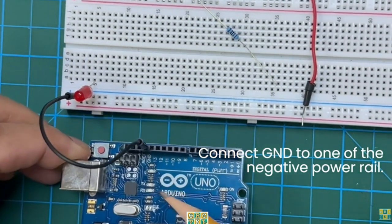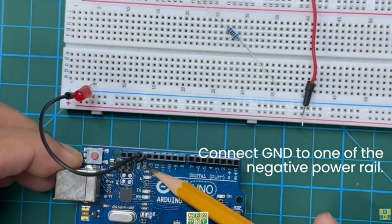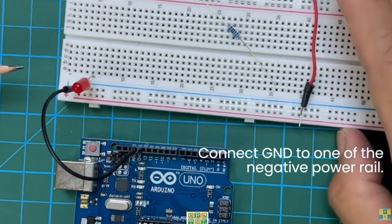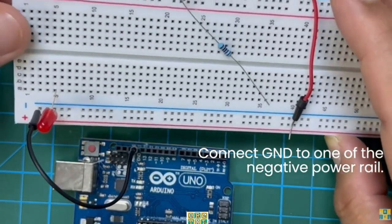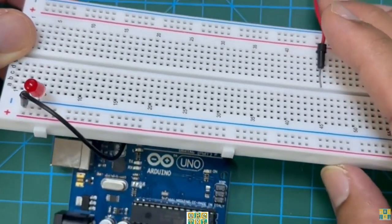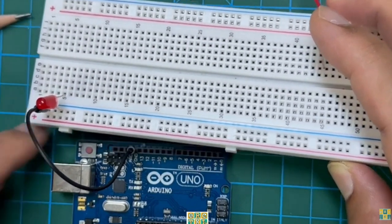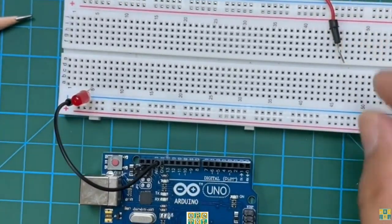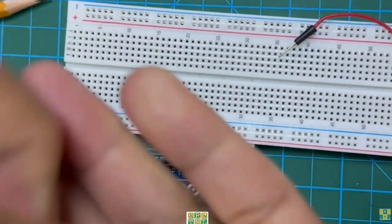So the negative horizontally are connected together. So we connect the GND of our Arduino to the negative of the power rail, as you can see here. I will upload this video later on, or there's a link I will provide to you so that you can go back on this example again. And now the other end of the LED is connected on A5.